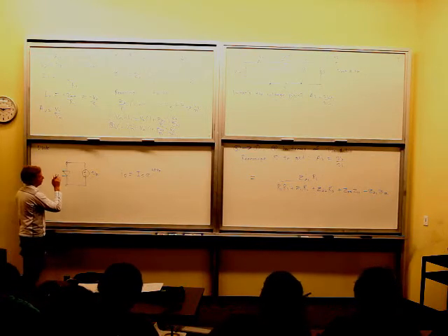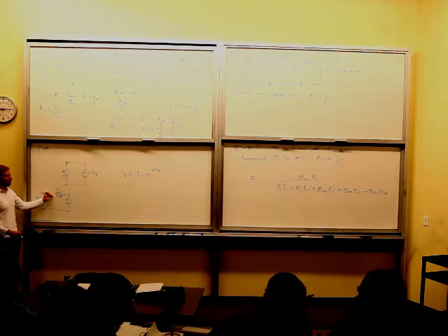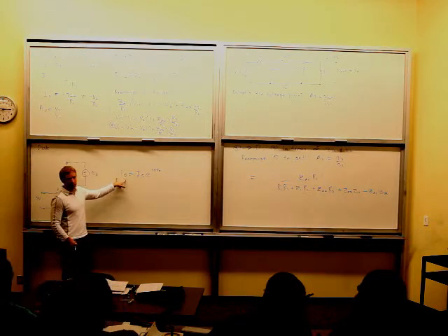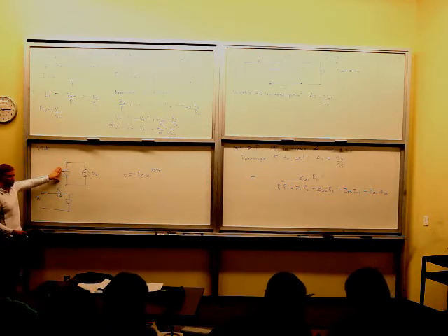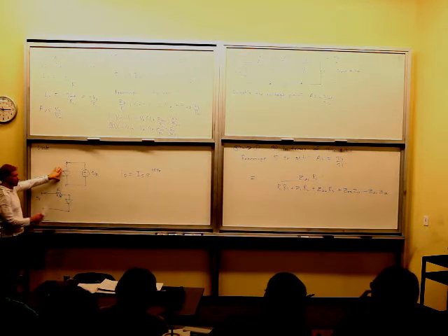Because that's just barely over 1 milliamp. So by putting a resistor in front of it, as designers we don't necessarily have to go to the exponential equation. We only have to go to that equation when we are directly controlling the voltage on the diode, or if we want to know exactly what the voltage across that diode is.